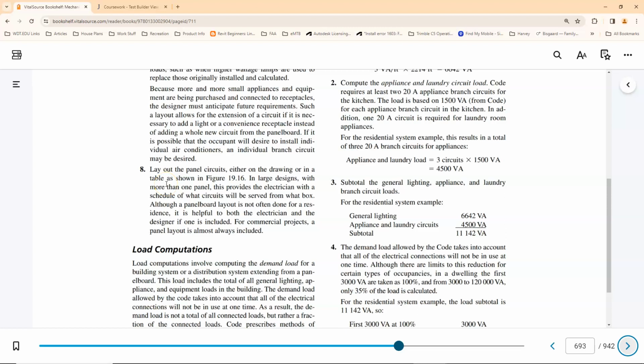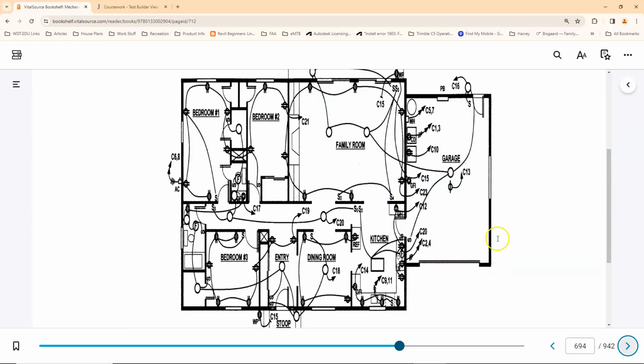So it's not really necessary to organize things, but if you want to put, for example, all of your lighting circuits, the breakers for those, all in one area, and then below that maybe your power, and then your high voltage stuff in another area, sometimes it's easier to find those breakers when it comes time to turning things off or tripping them back on.